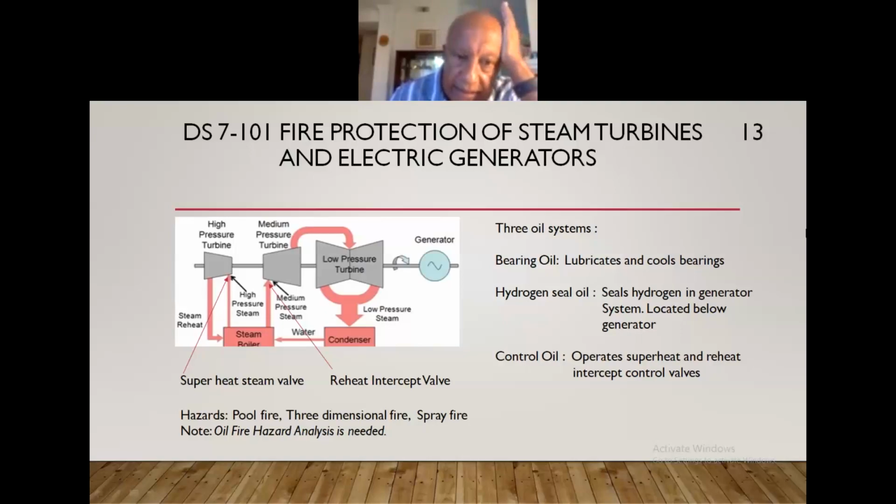So now we set the stage right. This machine, as soon as there is a fire, if we shut the oil down, all the bearings will run out and the rotor will settle down into the stator and make physical contact between the rotor and stator, and that will cause significant damage to the turbine. So this turbine is running at full load. Something went wrong. The master fuel trips. This machine will keep rolling for 40 minutes. Oil will be falling on the hot surfaces, ignite fire, and settle down in the condenser pit. It will burn there, and there will be a huge fire.